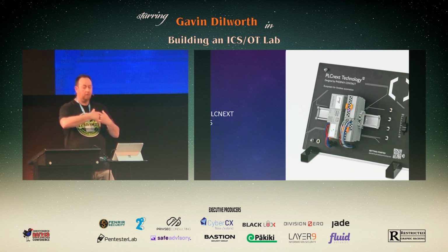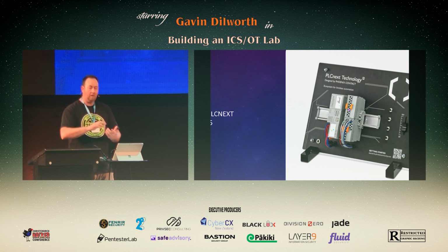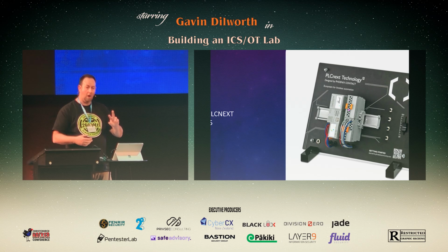So when you're speccing your PLC, you need to know that you've got the right input and output cards. An input card is a switch coming in, and an output card is something that you turn on, like a relay, or a solenoid valve, or a lamp, light, if you will. Those are digital, they're binary, like 0, 1, true, false, off, on.